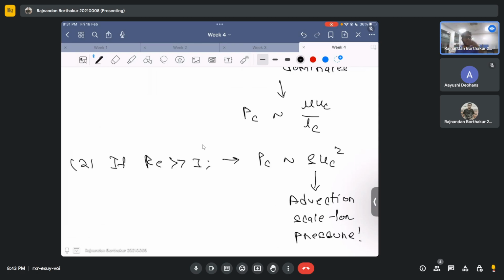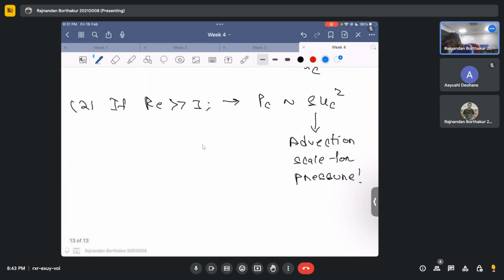The idea is that we will define certain non-dimensional quantities: the non-dimensional velocity, the non-dimensional time, the non-dimensional pressure. The non-dimensional quantities would be the dimensional quantities divided by the characteristic quantity. For instance, the non-dimensional velocity we will write as u bar. This would be the dimensional velocity divided by the characteristic velocity. This is a way of defining non-dimensional quantities, and that's why we define these scales in this manner. So this is the idea behind choosing the scales.